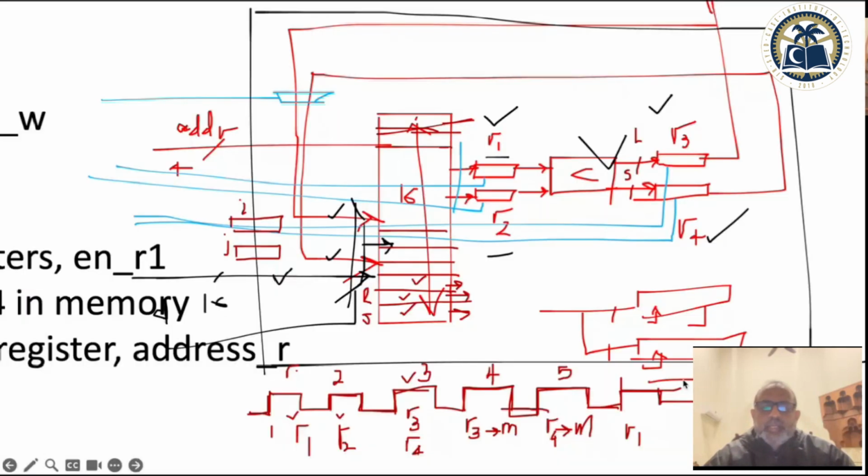And what we have learned in this is that first you need to be clear about what you are going to do. So you need to focus on your design at the RTL level. I just keep emphasizing that you design at register transfer level. You got to know where your registers are and any computation.